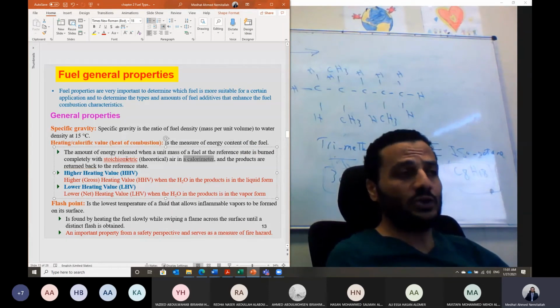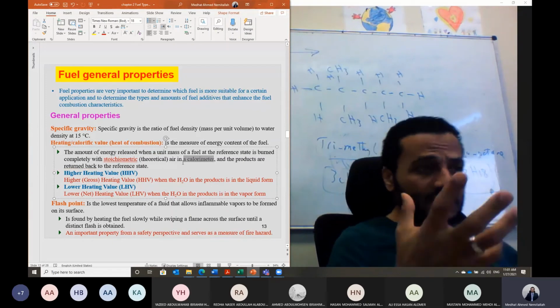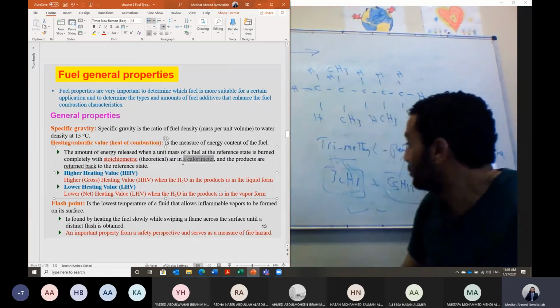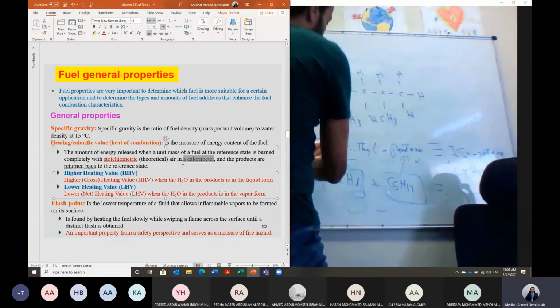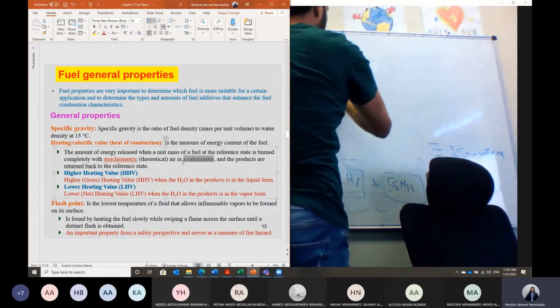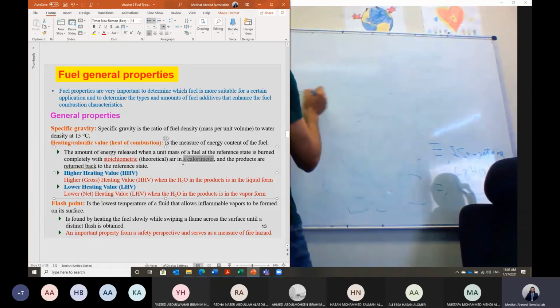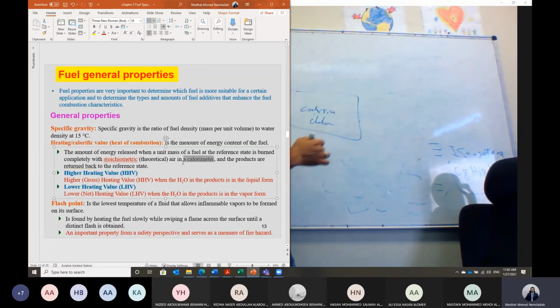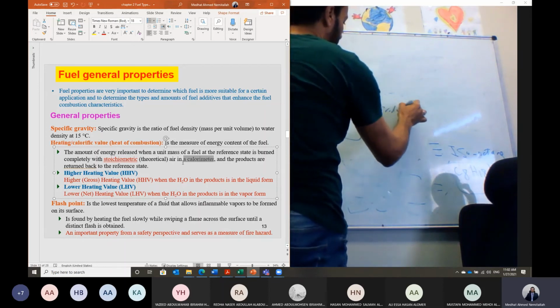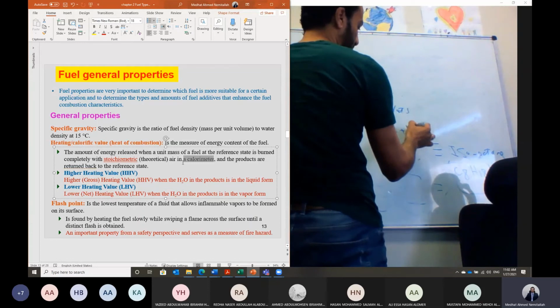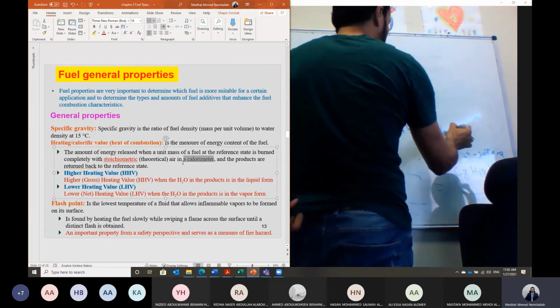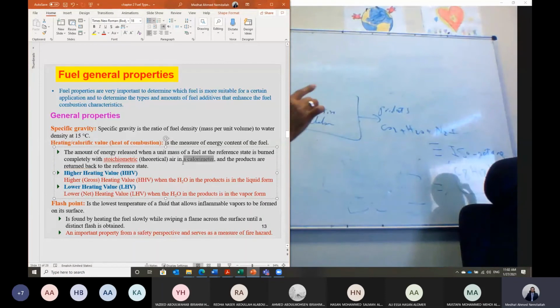It is the heat due to burning this fuel. And this water will make sure that the combustion products leave at the same inlet temperature. So in the bomb calorimeter, to calculate the heating value of the fuel, it's a kind of normal combustor. We bring the fuel and burn it with air inside the combustion chamber here, and then the combustion products leave here. The combustion products should be carbon dioxide, some water vapor, nitrogen, and some other components. This is a stoichiometric combustion.